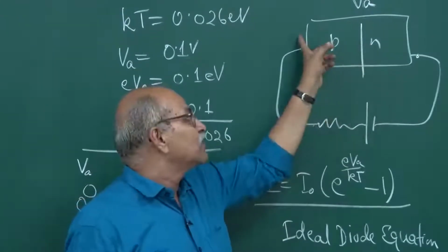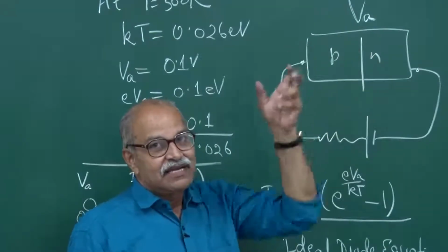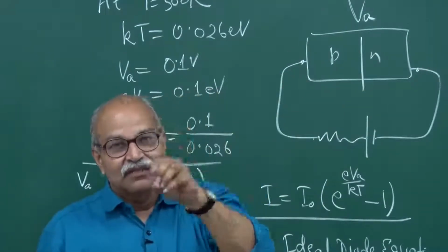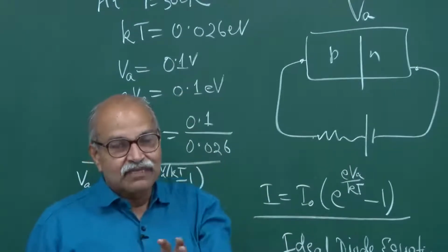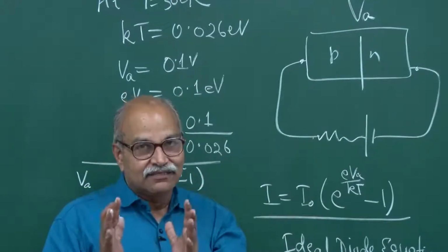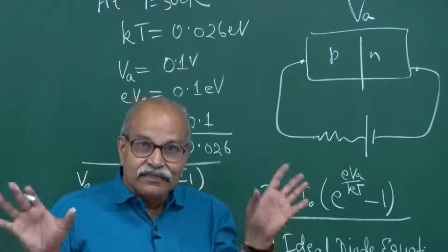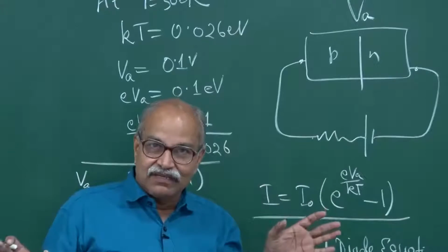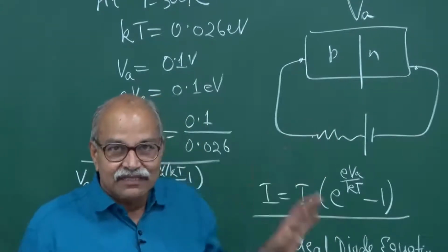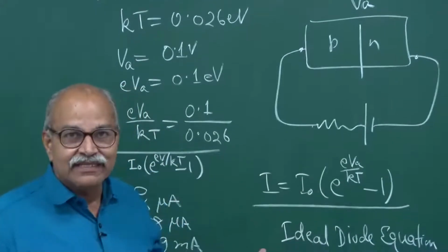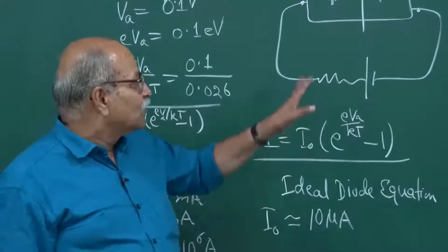Of course, the diode itself has some resistance to offer. So, whatever you apply here may not go on the junction. This depletion layer has a very small number, or negligible, we take it as 0, of charge carriers, but in any case that offers a very large resistance. The other regions outside the depletion region, where you have many charge carriers, offer less resistance, and in the ideal case no resistance in fact. So, all those things are there.